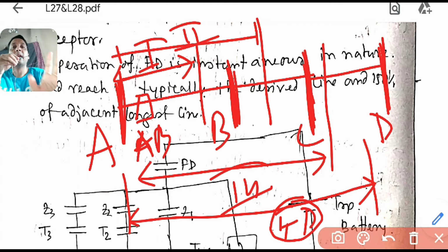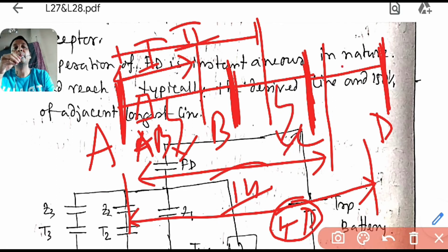That's it. Now we have given some intentional time delay. I will show you. First, think that if there is any fault, all relays will sense it. Then obviously if it is here, step 1 will not sense. If it is here, then all will sense. If it is here, then obviously only step 3 will sense. Step 1 and step 2 will not sense, because in that case RAB is not your primary. It will come under step 1 of RBC.